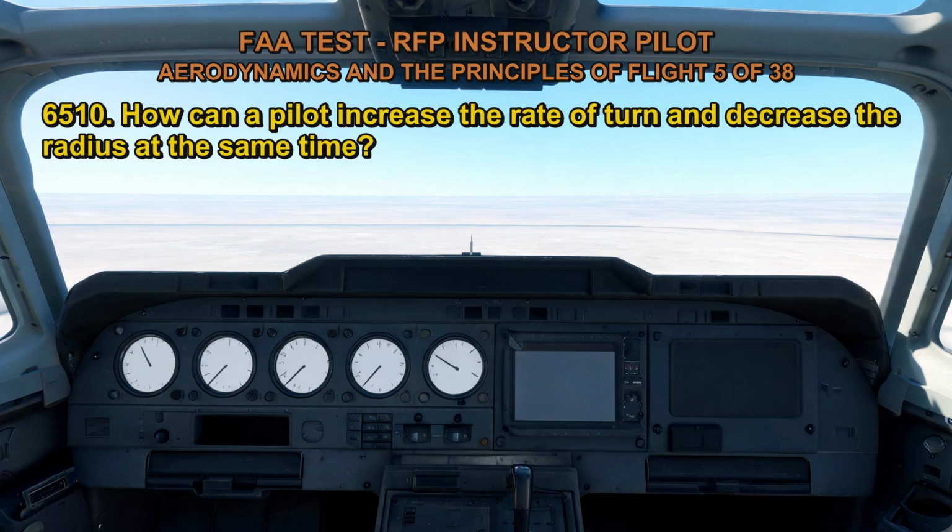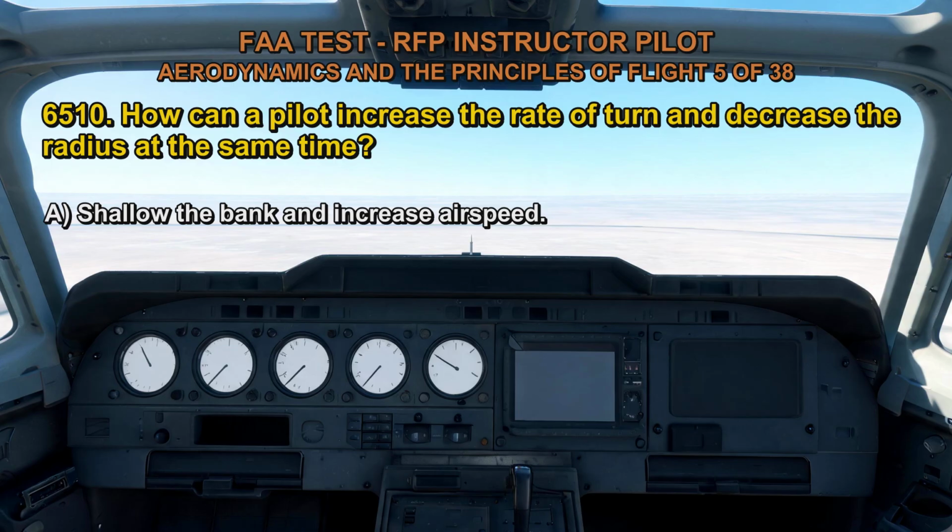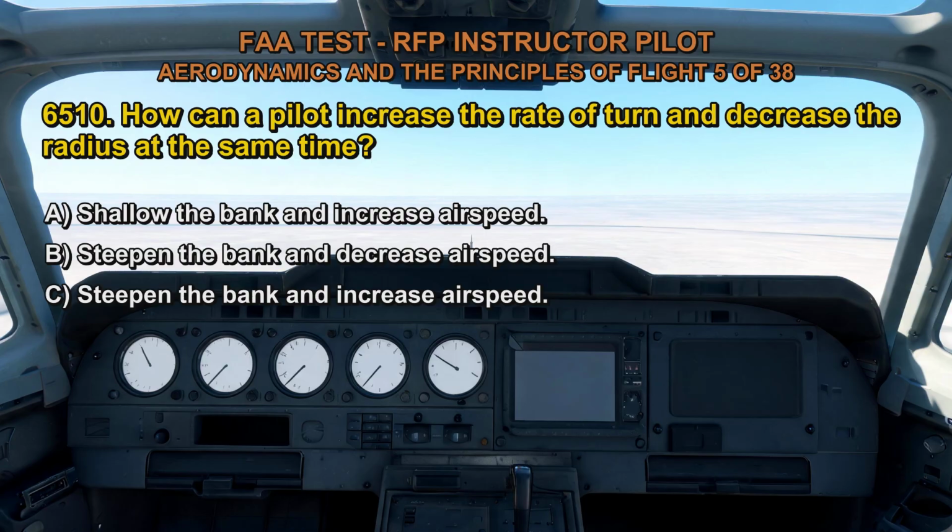6510. How can a pilot increase the rate of turn and decrease the radius at the same time? A. Shallow the bank and increase airspeed. B. Steepen the bank and decrease airspeed. C. Steepen the bank and increase airspeed. The correct answer is B.